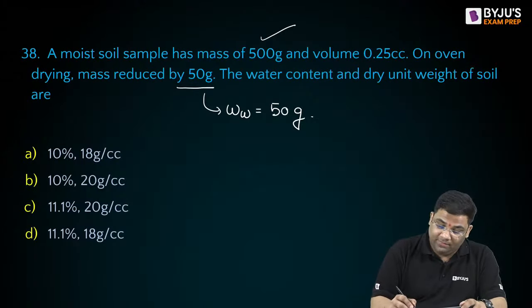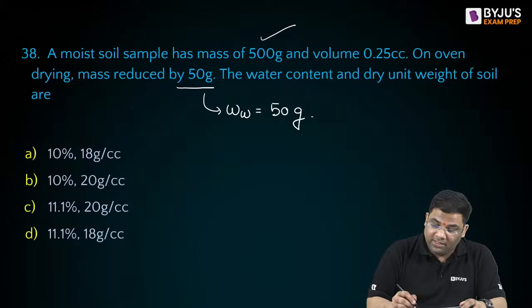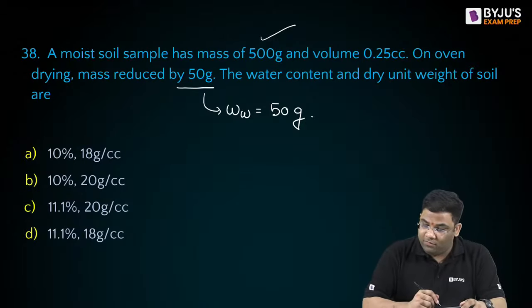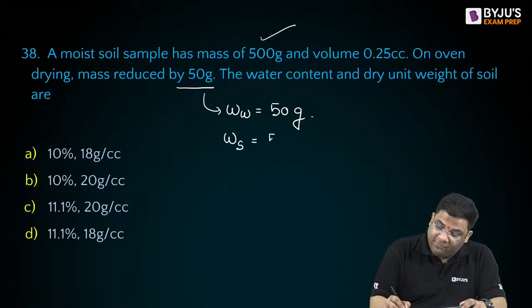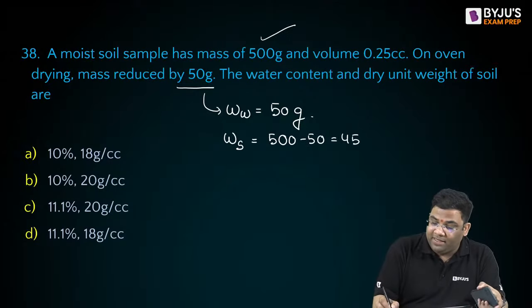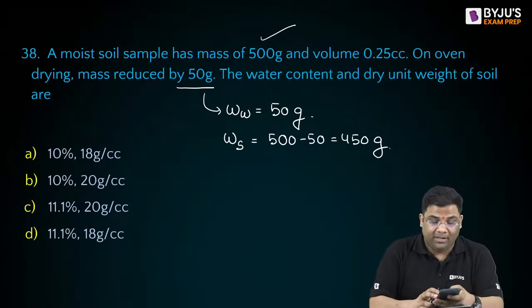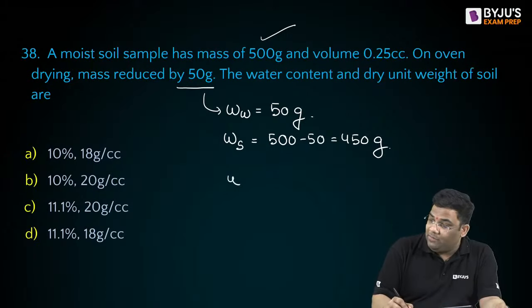So what is the water content? The weight of solids will be how much? 500 minus 50, giving me 450 gram. So what is the water content? Tell me. The water content will be how much?